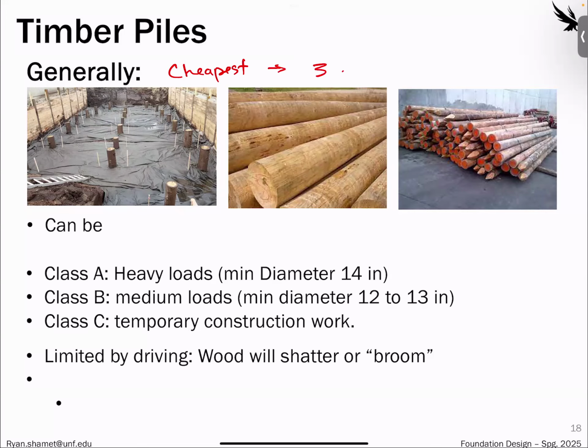They're classified into 3 categories. Good thing with these is they can be driven. They can also be pushed, which is nice. So you can sharpen it and you can actually just get a hydraulic push, like a counterweight for some of these lower capacities and just hydraulically push them into the soil.